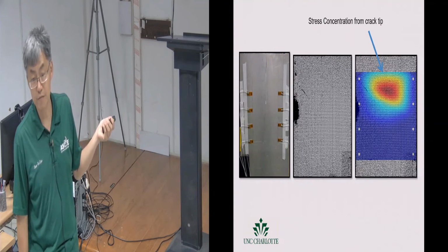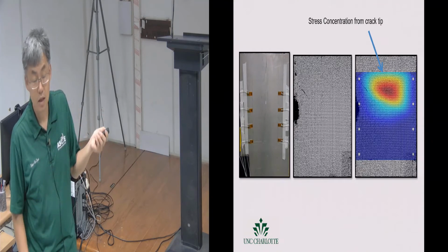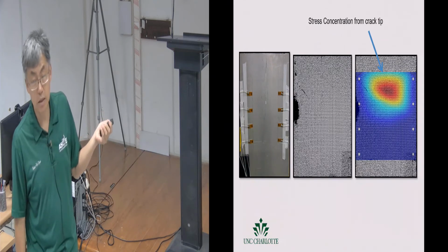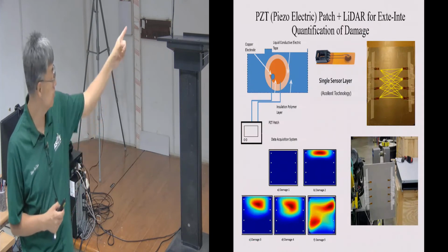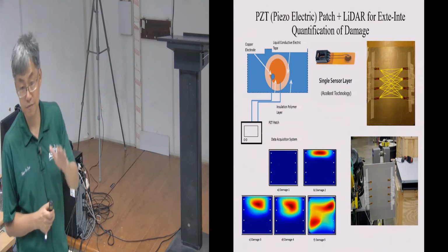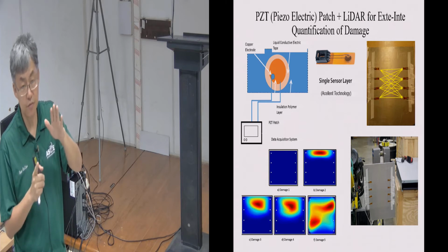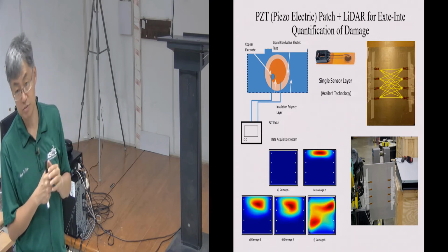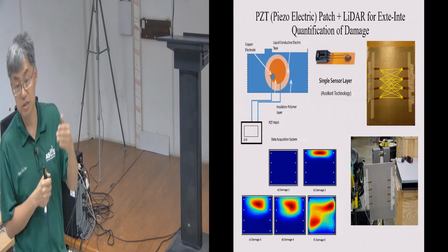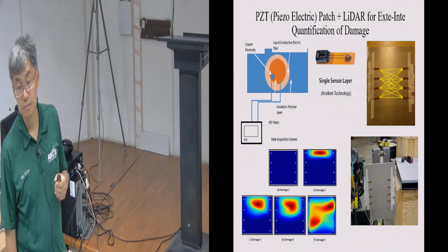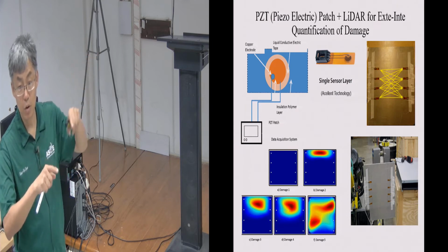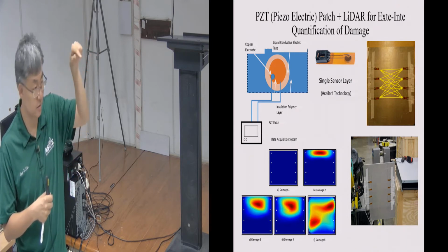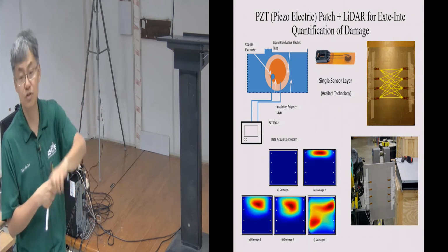Excitation is the wave, vibration. That's a good question. I believe it's a band of frequencies. Because the piezo size is very specific, the vibration of the plate, but the difference is you can actually excite different modes of vibration, and that's how you create different frequencies of waves. Yeah, you can decide, or you can automate. So one sensor would excite, and then the second sensor, third sensor, you can actually generate that algorithm.